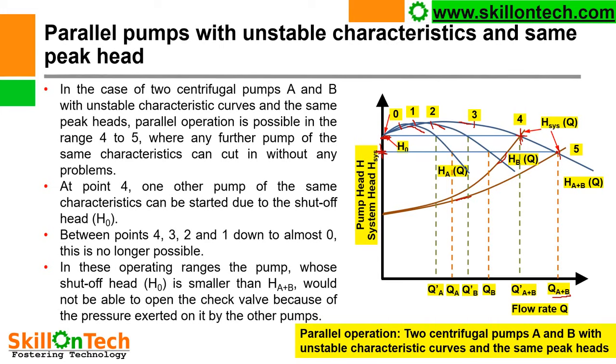Therefore it is very important to know where we have to operate parallel pumping with unstable characteristics, and at what operating head we have to run the pumps in parallel.